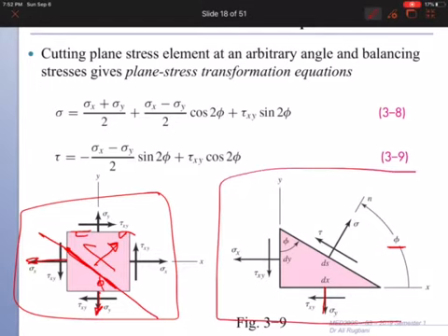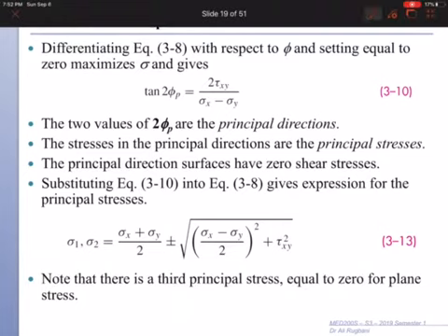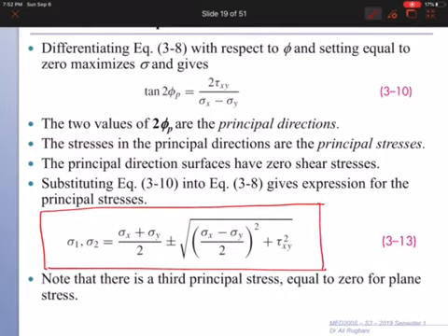Here. So this is the maximum stress value, the principal stress, and this is the shear stress. Okay, now the formula to calculate plane stresses is this formula. Once you have your sigma x and sigma y and shear, you can calculate sigma 1 and sigma 2.